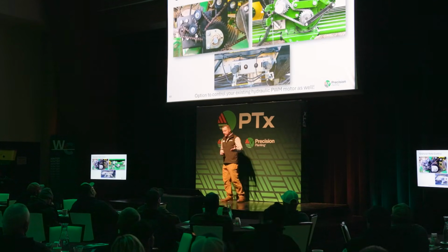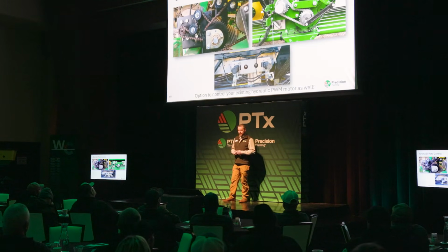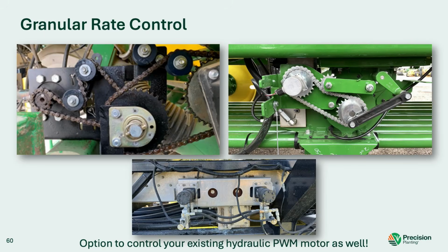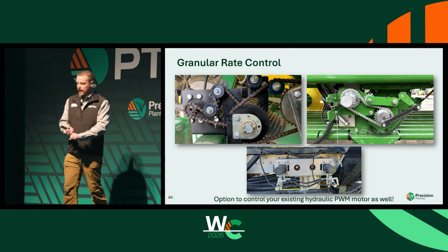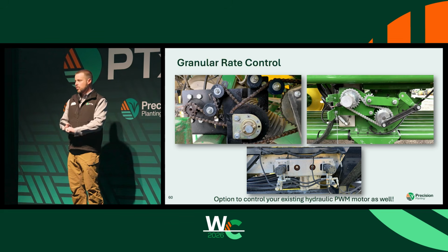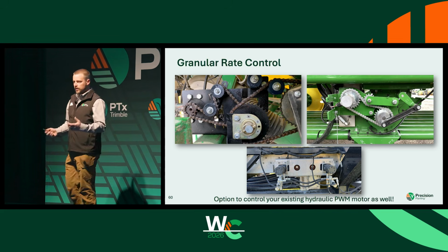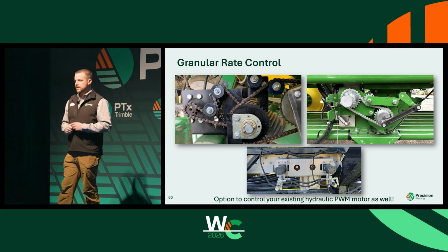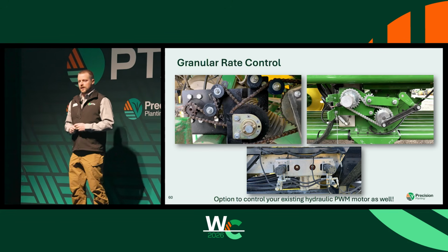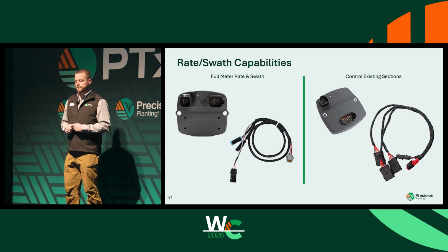Now, if I'm looking at a 1990, as well as I've got a hydraulic drive cart that already has the hydraulic drive on it, we do have brackets for 1990s as well as harnessing to convert my hydraulic drive 1910 to run everything through the 2020 if I choose to do that. If your machine's not listed up here, I've got something different. I've got a strip-till applicator I want to monitor and I want to run through the 2020. Talk to your dealer. We have availability to control other hydraulic drives as long as they meet some of the constraints as it relates to the valve type and some of the sensors that are on there.